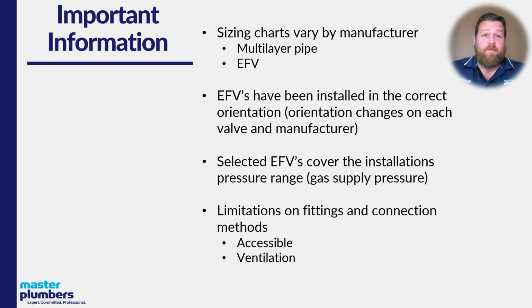So some important information here. The sizing charts vary manufacturer to manufacturer. That's across the multi-layer pipe and the excess flow valves themselves. So ensure that you are using the method that they stipulate in their installation guides, and also the figures that they use in their sizing tables.